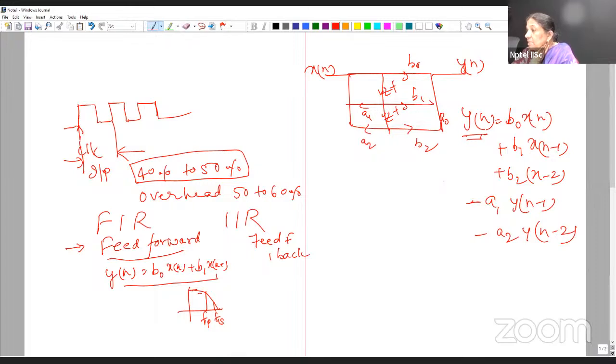And why we need the cascade section also, because if we consider the complete direct form implementation, if any one coefficient is modified a little bit, the entire section gets altered. So everything has to be looked into. Whereas in this second order section, whatever perturbation is going to happen is restricted to this section. I think I've covered it more elsewhere. Just to give you a hint, I'm putting it here. So that is how we get whatever the order of the filter.